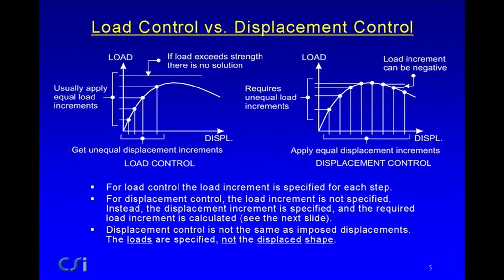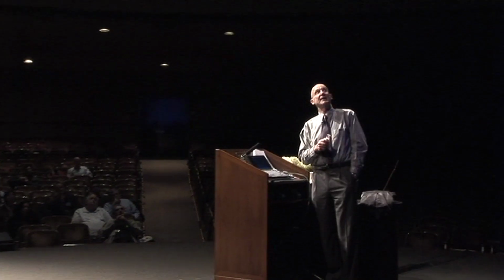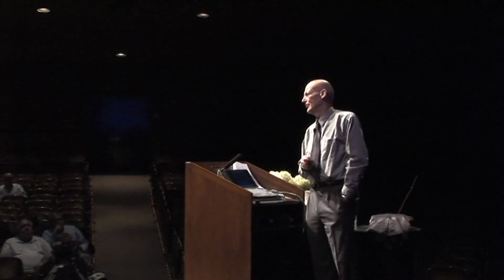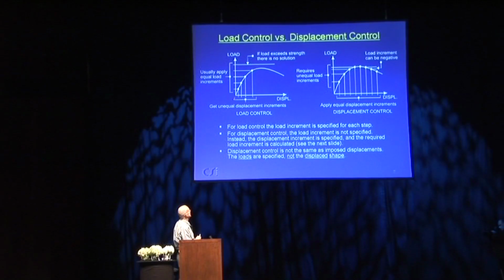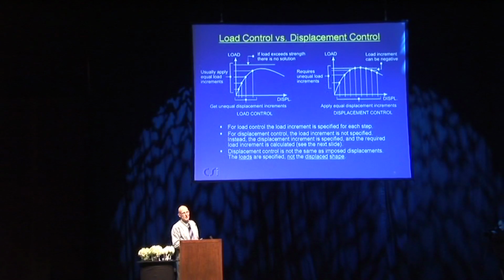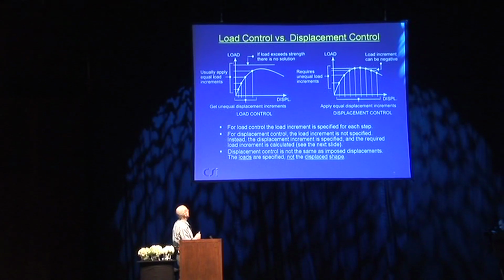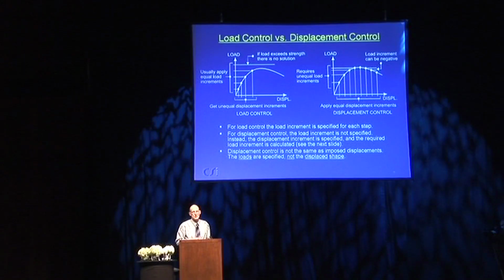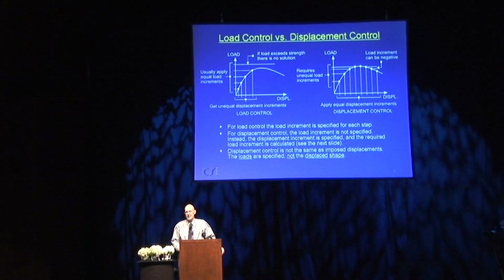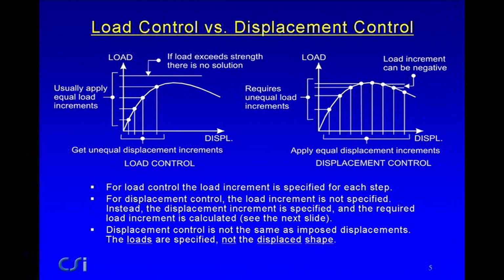Load control first: you apply a number of load increments, typically uniform but not necessary, and what you'll get is, as you apply uniform load increments and the structure gets softer, the displacement increments will get progressively larger. And if you try to apply a load which is larger than the strength of the structure, there is no solution, and the analysis will simply not be able to find a solution and will stop. So this is not a very good method of doing static pushover.